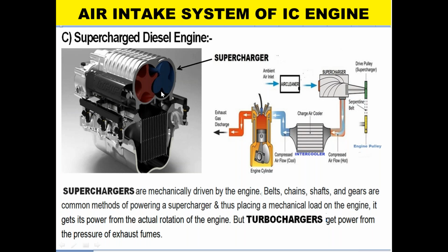You see the supercharged diesel engine. Try to distinguish between the supercharger and the turbocharger. The construction of the supercharger is different. These are the two rotating wheels. Here, again, the ambient air enters the air cleaner, then it enters the supercharger, which is driven by the engine pulley. Mind it, it is driven by the engine pulley. And then the compressed air flows to the intercooler where it is cooled down, then it enters the combustion chamber where it is burnt with the air fuel mixture, and then the exhaust gases are discharged from here.